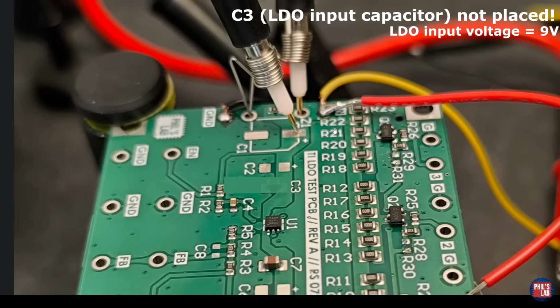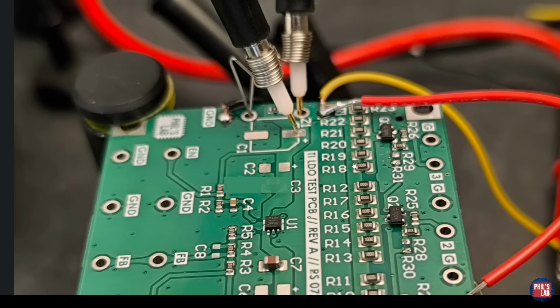So again, we're following this image with the two Bode 100 input probes, so channel 1 and channel 2, effectively shorted together. We have the line injector connected to the input, and the LDO is supplying 150 milliamps of current. So this is our baseline operating point, and we want to bias around this. Keep in mind, C3 is not populated because the output impedance of our line injector is actually resistive. So if we keep C3 populated, we actually have a low pass filter which will distort and alter our actual PSRR measurements. So the input capacitor, in this case C3, is typically depopulated in PSRR measurements.